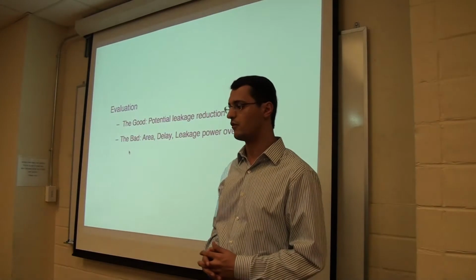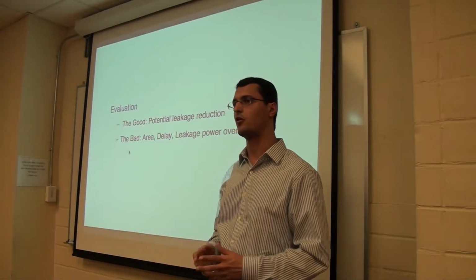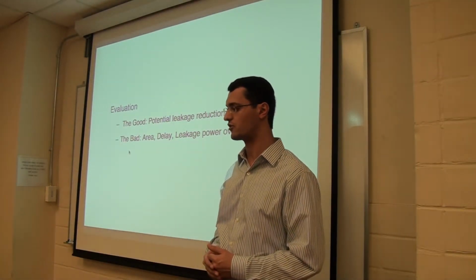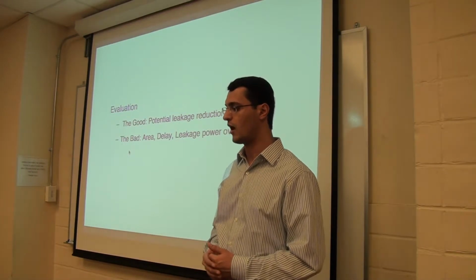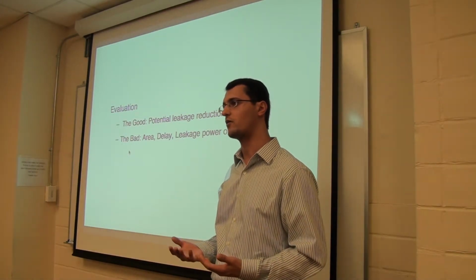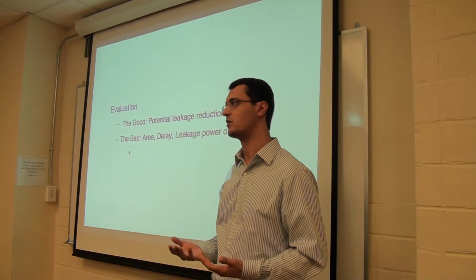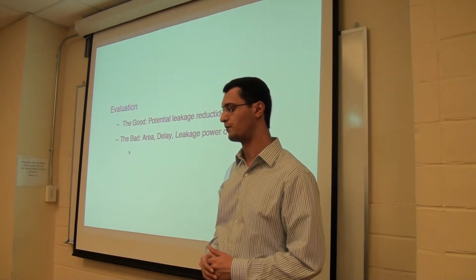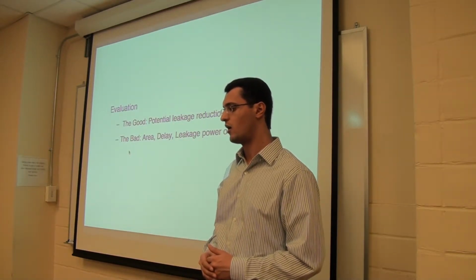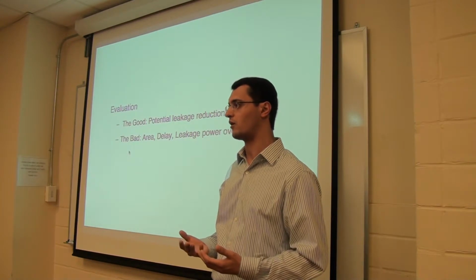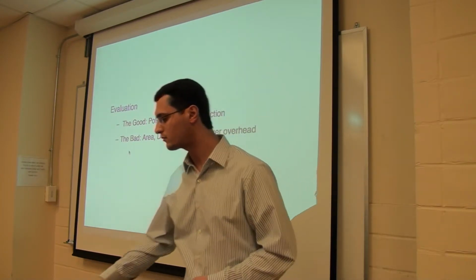So we did evaluation for this architecture. The good is the potential leakage power saving in sleep mode. And the bad is the area overhead, the delay overhead because of the sleep transistors that exist in our architecture. And there's a leakage power overhead during the on state.